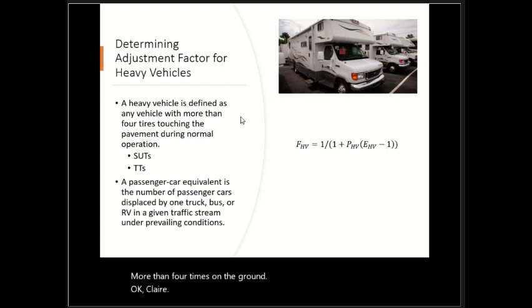So, what is EHV? EHV gives you the effect of one heavy vehicle in comparison to a car. Now, which one is bigger, a car or a heavy vehicle? A heavy vehicle is bigger, right? In most of the cases. Some of us have big cars. Okay, good for you. Get out of my class. But mainly heavy vehicles are bigger, so they take more space. So the space taken by one heavy vehicle could be the same space in which you may fit more than one car, right?